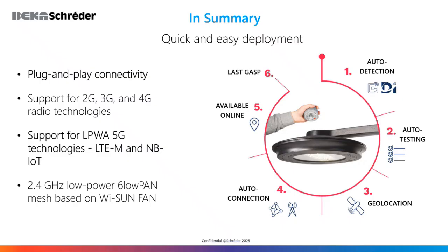A gateway-less system, our Owlet 4 devices has no gateways. This makes the communication and the maintenance process much simpler and easier to handle. When we say auto commissioning, it means additional installation tools aren't required. Once the node is plugged into the socket, the process includes an automatic self-test. After this process, the controller literally pops up in the user interface with its accurate geolocation.